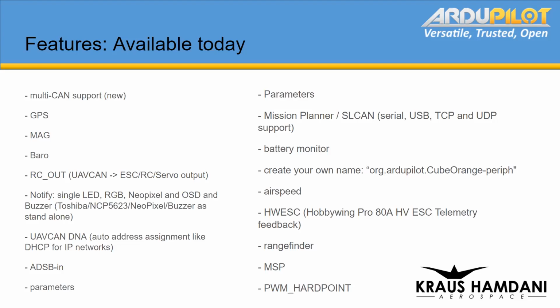In fact, the buzzer itself I've used on the vehicles I use at Kraus Hamdani Aerospace. We don't have a buzzer on the aircraft, but it's nice to know when it reboots, if you're doing firmware updates or whatever. Everything on it is CAN as much as possible on all of our new development. So I can just plug in a Cube on a carrier board anywhere on the end of the wing or something, and then suddenly I have a buzzer that I can use to know when it reboots, which is kind of convenient.